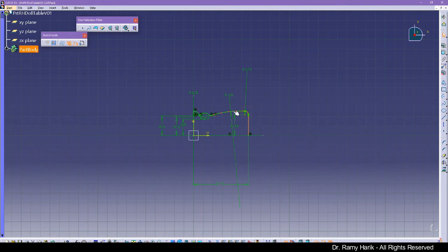Then I wish I did not click somewhere else, because I could have just directly created the mirror, the first mirror here, with respect to this axis, and then I can click. So let me demonstrate this filter. This one actually would select all curves. So I can click all these curves. We don't need this one, we don't need that one, we don't need this one, and we can actually create another mirror, and this time with respect to the axis in here. So what did I select? I should not, I don't know. So let's go ahead and select.